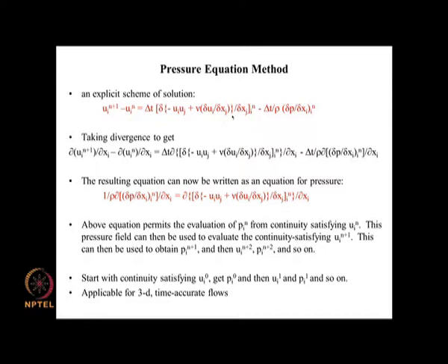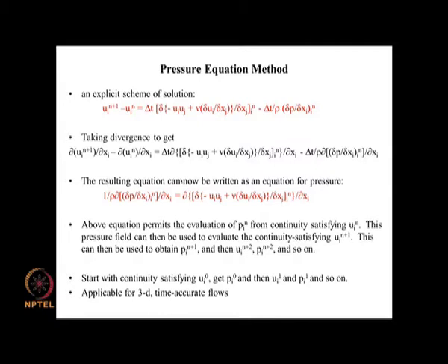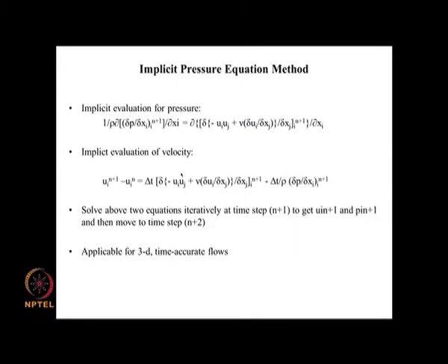This is an explicit solution, this is an implicit solution, and when you are looking at coupled equations, an implicit solution is better, it is more stable. So in that sense you can have much larger delta t's with this than with this, and that is the advantage that we get.